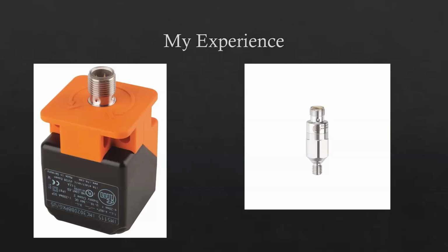This vibratory sensor is strapped to the cutting piece of the CNC device, and it measures the vibrations and temperature of the system. And we can use this data, average it to see when the crest or the amplitude of the wave is getting too high. We can infer that there's an issue with the CNC milling device, which can cause poor fridge gasket output. So the whole idea here is making sure that we keep our vibrations consistent, steady, and low.